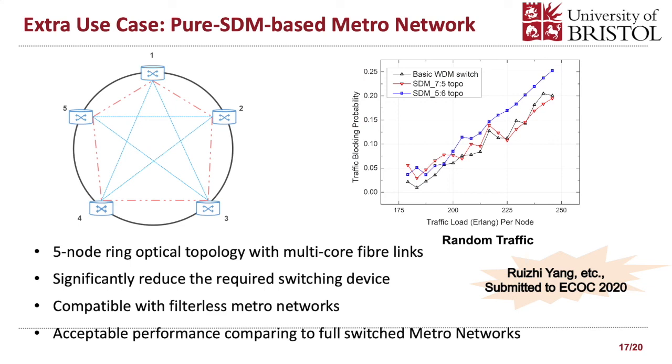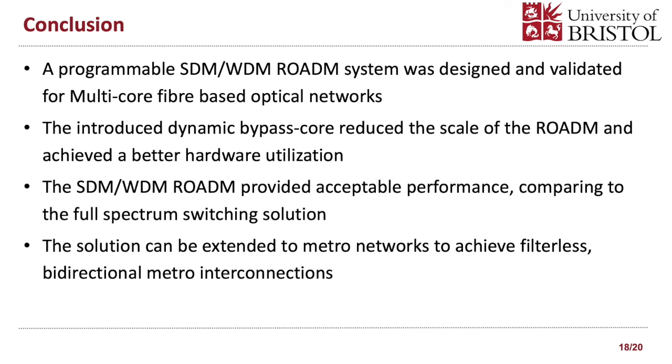So I think here I can conclude my talk. We have discussed our design of a programmable SDM-WDM ROADM system, and we validated it with simulation. The dynamic bypass core solution reduces the scale of the ROADM and achieves better hardware utilization. The SDM-WDM design provides acceptable performance compared to a full spectrum switching solution, and reduces the complexity of the routing algorithm. This solution can also be extended to metro networks to achieve filterless bidirectional metro interconnections.